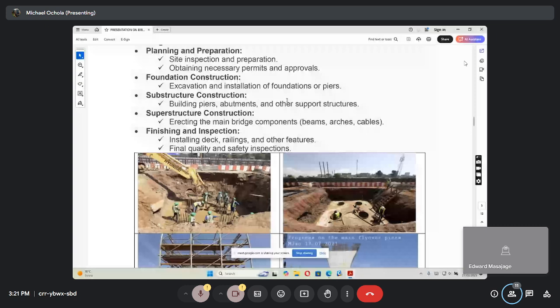Looking at the sand, the stone, the cement, and maybe an admixture somewhere. Water. So if you have an automatically managed batching plant, then you feed in those things and it will control it for you. If you are dealing with smaller sites, then you batch by volume. This could also be by weight. So now these are some of the things that even there's quality control on where to place, so you can see the site arrangement. If you can see these sheds, these are what we call